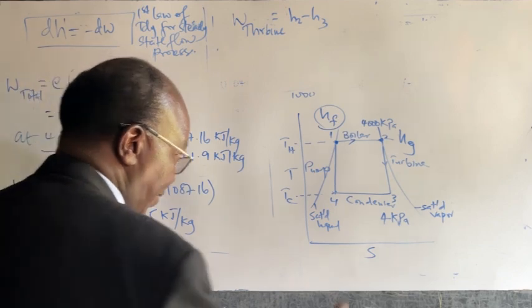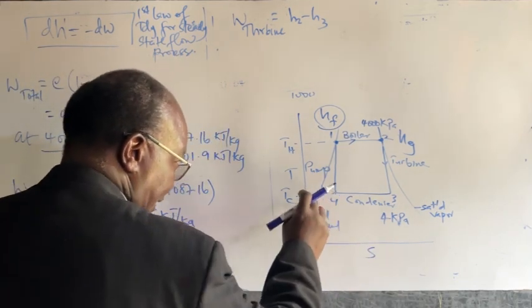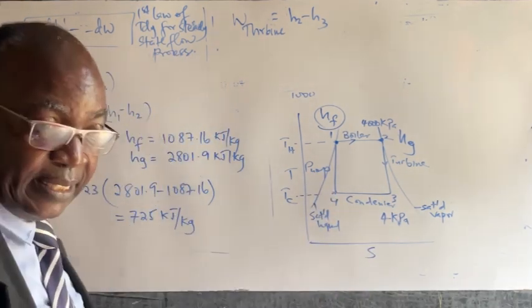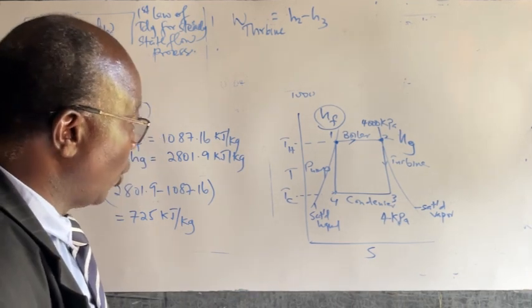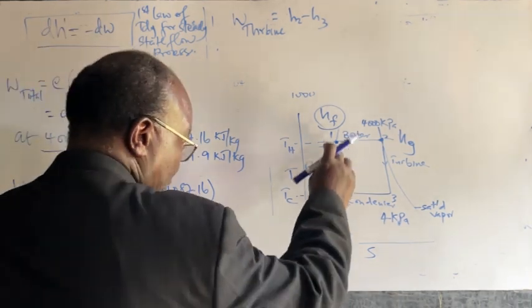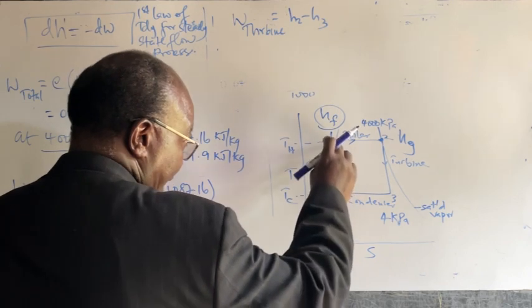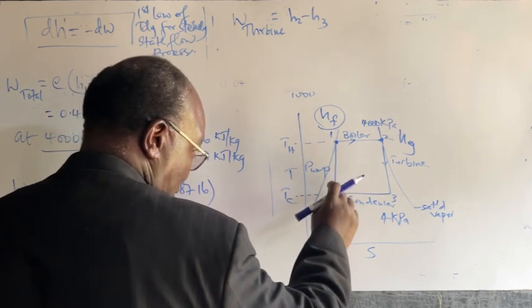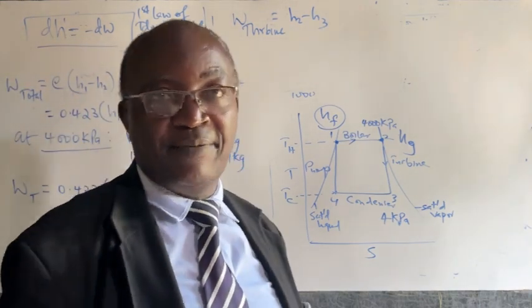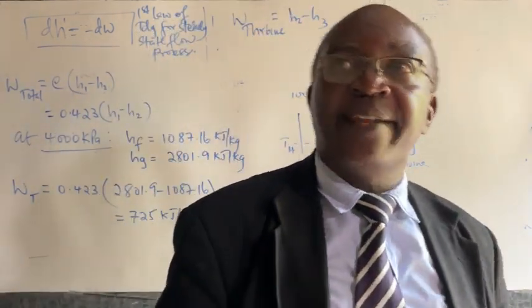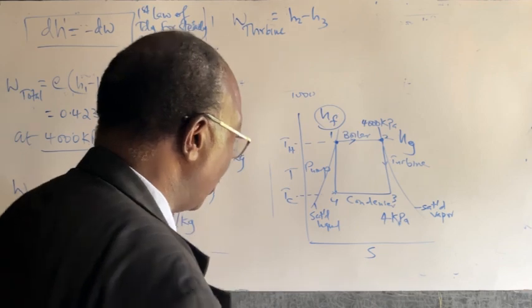In the same way, we have the condenser here. State point 4 does not touch that saturated liquid curve. But we know that this process is adiabatic from 4 to 1 and it's isentropic. So again, the entropy at S4 and S1 are the same. Entropy is another thermodynamic state function, and there are relationships between these functions. So we can use that.